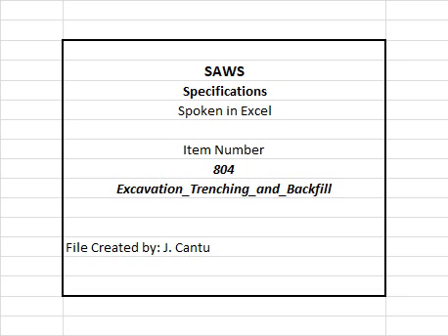8. Texas Department of Transportation, TXDOT. A. TXDOT Tex 101E, Preparing Soil and Flexible Base Materials for Testing. B. TXDOT Tex 110E, Particle Size Analysis of Soils. C. TXDOT Tex 112E, Test Procedure for Admixing Lime to Reduce Plasticity Index of Soils. D. TXDOT Tex 113E, Laboratory Compaction Characteristics and Moisture Density Relationship of Base Materials. E. TXDOT Tex 114E, Laboratory Compaction Characteristics and Moisture Density Relationship of Subgrade, Embankment Soils, and Backfill Material. F. TXDOT Tex 142E, Laboratory Classification of Soils for Engineering Purposes.